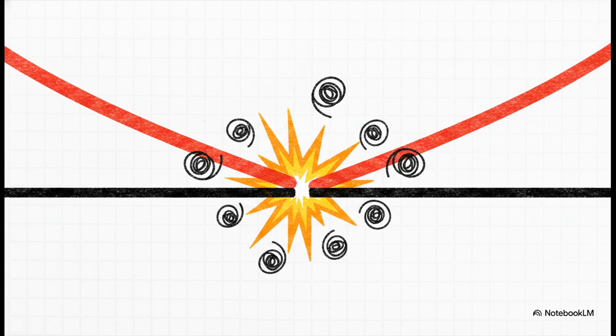Because these two separate phases are literally touching each other and the Earth at that exact same spot, boom, it creates a direct phase-to-phase short circuit. The fault current doesn't have to travel across the network at all, it just seeks the path of least resistance right there at that single point. The short is immediate, it's localized, and it is extreme.